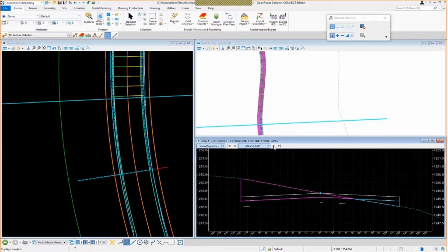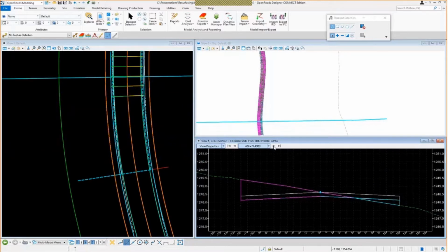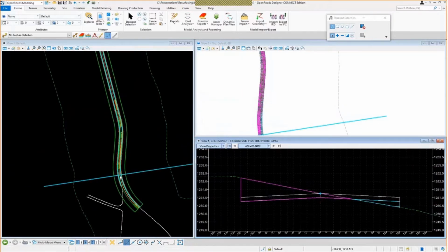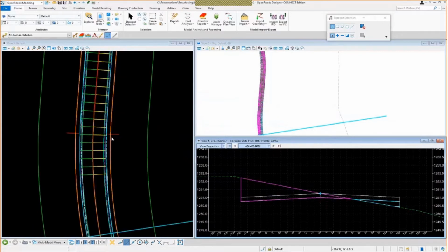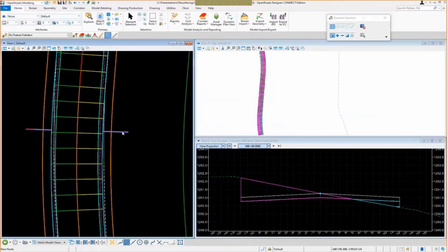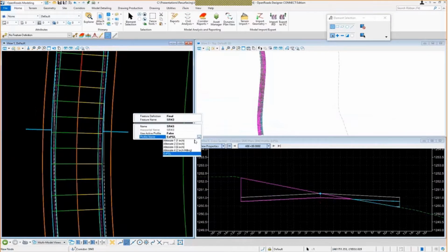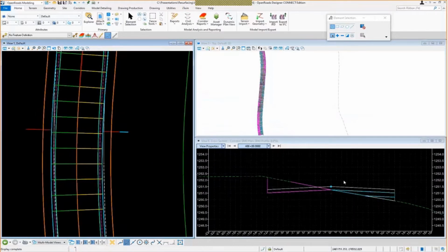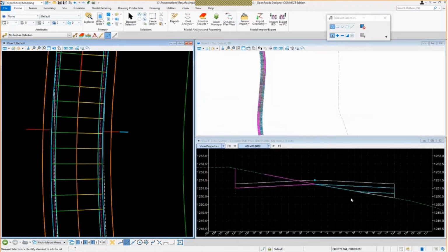You might have to raise up the profile so you can see this better. Okay, so let me change the profile on this so you can better see the multiple layers. I'm going to swap out my profiles. Right now we're following existing ground. I'm going to select one of my alternate profiles in my geometry file. So I'm going to select alternate number 2, raise this up about 3 inches. Now you'll be able to see those layers a little bit better.